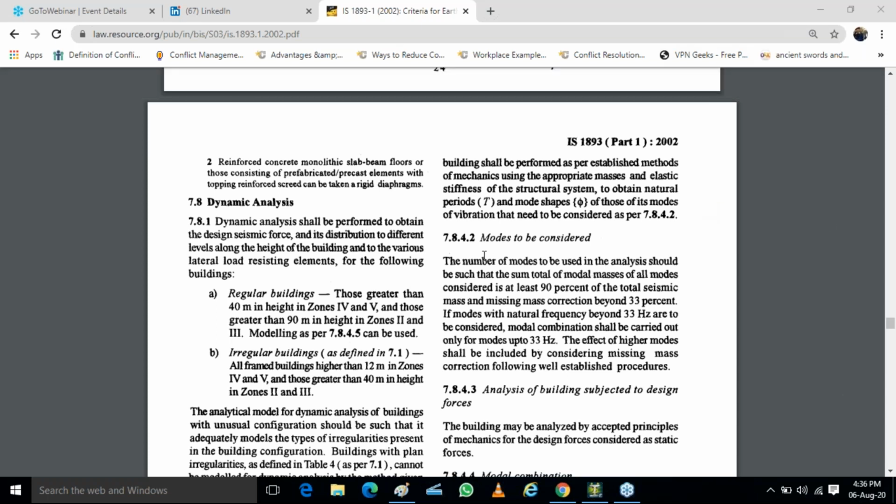No one. Okay, this clause is saying that of the modes of vibration, only those vibrations will be considered in which the modal mass, which is the WI, is around 90%. Means if I am doing an analysis or participating, suppose I am giving you training, my participation is 50% because another 50% will be from your side. If you will not perform, there is no use of teaching.